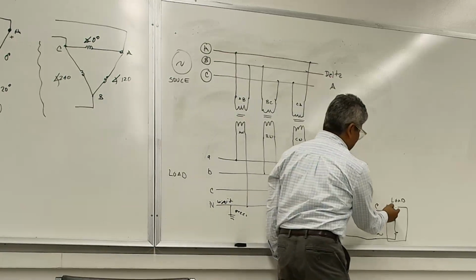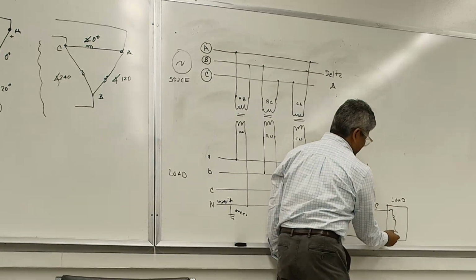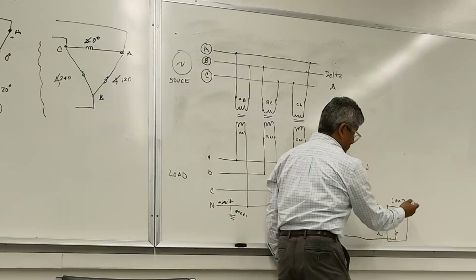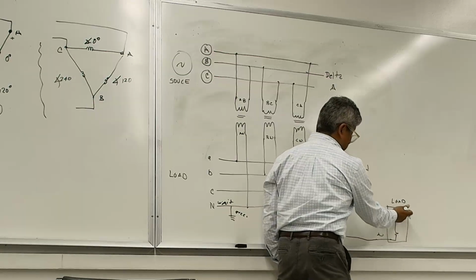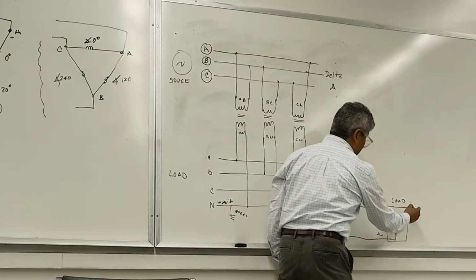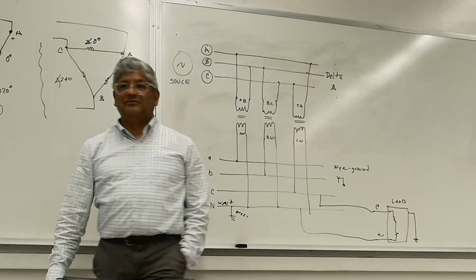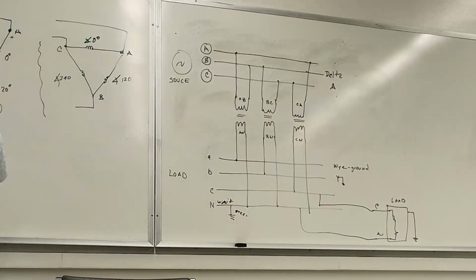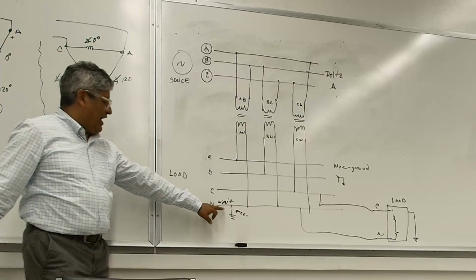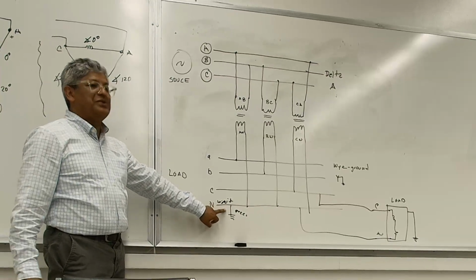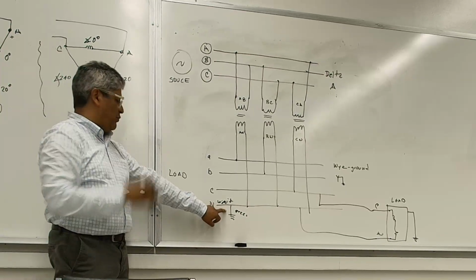If you're in the lab with me this semester or with somebody else, you'll notice we have the boxes, the benches will have a green wire going to ground, okay? Here, as I said, you can do this on a wye grounded system, a wye grounded transformer.